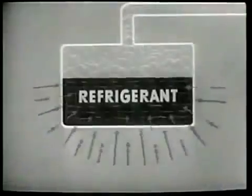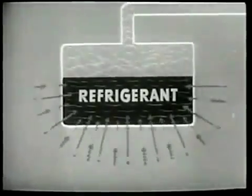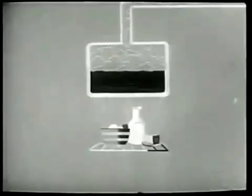The principles of refrigeration are physical principles applied as follows for the purpose of removing heat and reducing temperature. First, mechanical refrigeration rests on the ability of a refrigerant to absorb heat while changing from a liquid to a gas, and to release that heat while returning to the liquid state. Second, when the pressure on a liquid refrigerant is reduced, the liquid boils at a lower temperature. Third, the transfer of heat from food items or other warm surroundings to a liquid refrigerant involves three processes: radiation, convection, and conduction.